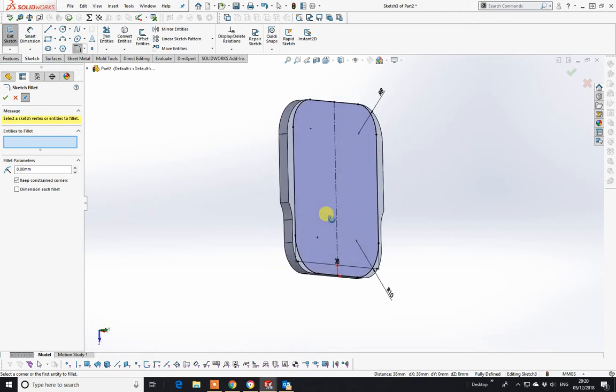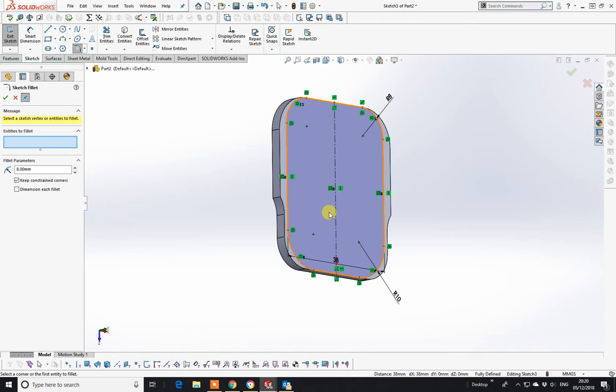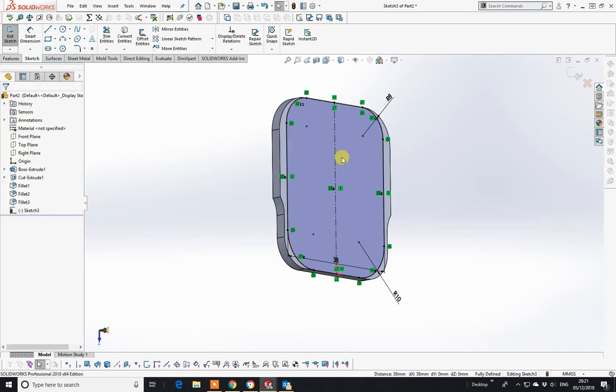Now two things, you'll notice that's on that surface there. Now in reality this should have a draft angle on it. So I need to be off that surface. And I can't actually remember the actual depth of that, but let's say for now it is 6 millimeters. Actually, I'll just double check that. So using your verniers, just measure, it is actually 7 millimeters on there.